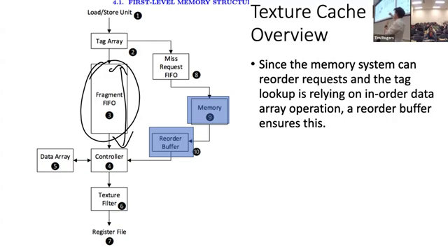Okay, because if you're doing LRU replacement on the tag array, so you have some stream of accesses you're doing LRU replacement on, you're going to do the same LRU replacement on the data array, and you're going to process the tag array and the data array in the exact same order. Then by definition, a hit up here will correspond to a hit down here and vice versa. If you guarantee the order, which we are doing because we're doing this reorder buffer business. Okay. Make sense? So even though it's not actually happening temporally at the same time, it's logically happening at the same time because the orders are enforced and the sizing is the same. Does that make sense? Okay, yeah.